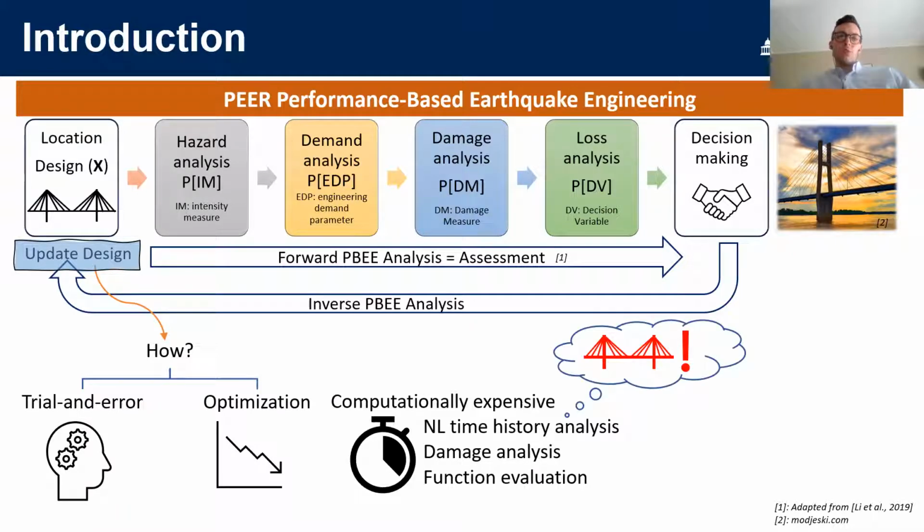Whichever of these ways we choose is going to be really computationally expensive. This is mainly due to the requirement to perform nonlinear time history analysis, which is really expensive for cable-stayed bridges because it requires the consideration of all the sources of nonlinearity that they have.